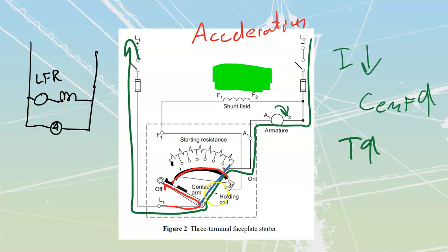Now this relay is a magnetic relay. It creates a magnetic field, a very small blue magnetic field around it. That magnetic field is designed to seal in up against that little magnet that we see over there on the contact arm, so it is going to hold this thing in. All we're going to do is just do this one push, tick, tick, tick, tick, tick, tick, boom, and then it's going to get held in by a magnet. Remember, there's spring tension trying to pull it back.